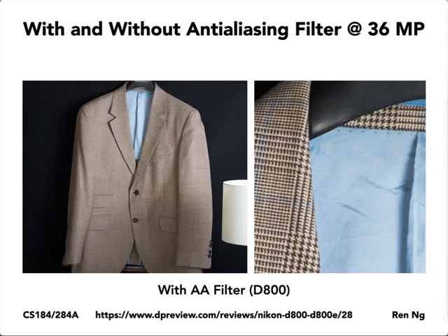Anti-aliasing is something where you have to filter out the high frequencies before you sample. You cannot sample and then filter out the high frequencies, which is what Brian is describing, saying, why don't we just take the picture without the anti-aliasing filter and then solve the problem in software, just blur it afterwards. Filter then sample is not the same as sample then filter in this anti-aliasing sense.